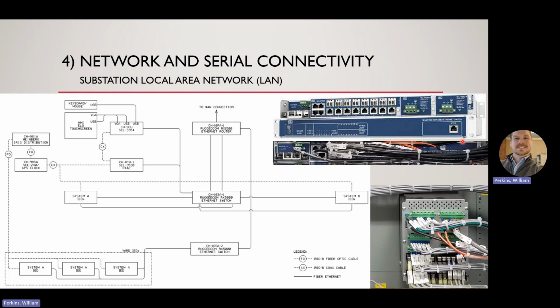One of the ways is via a serial connection, which is typically a point-to-point connection. So an IED would have a DB9 serial or a fiber serial connection and would connect directly back to the RTU that way.